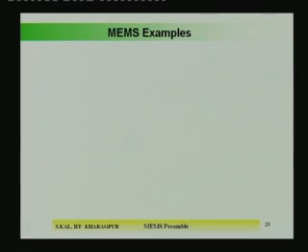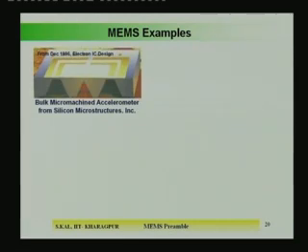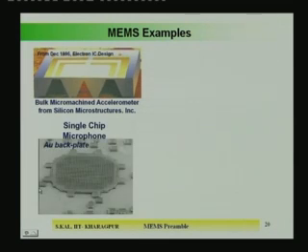body. Now, a few other examples I am showing here: a bulk micromachined accelerometer from silicon microstructures. Here you can see this is the bulk, and here is some kind of membrane, and from there some structure has been made. This is another, a single chip microphone, and that is the gold coated back plate, and here is the structure, basically a vibrator, and then the other circuits, because in a microphone first the acoustic signal is received, and that is converted into an electrical signal, and that signal is again amplified electronically. So, the whole thing can be made out of silicon.